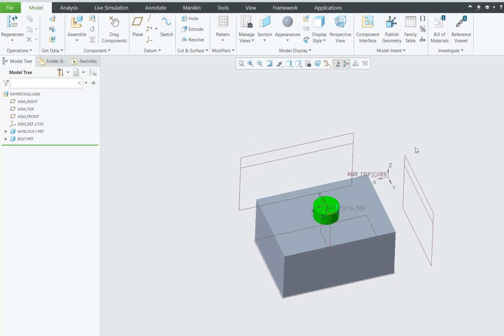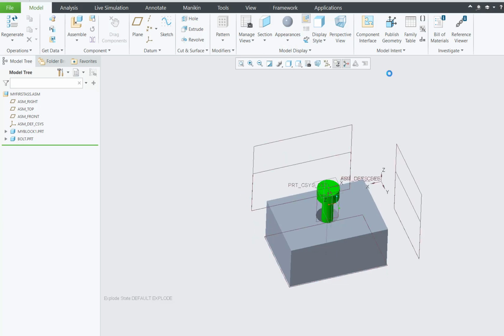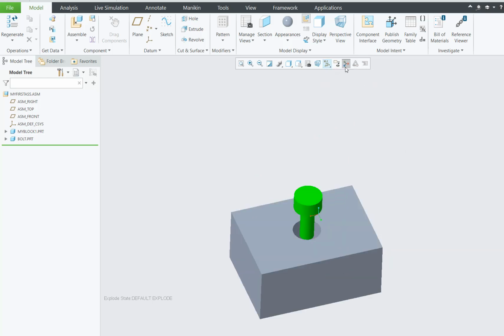So let's say if you have this assembly, now you want to make, for example, an exploded view. Okay, all that you need to do is explode. You hit that, it will pull that one and show how parts are connected to each other. And this one I can get rid of by using this. You go to here and select all, clean. This is spin center, you can get rid of it like that. Okay, so this is a simple assembly of a part.